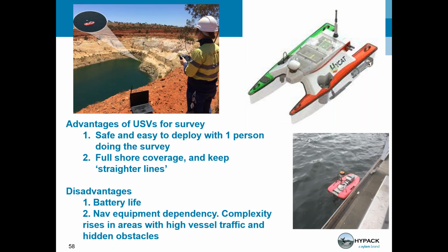Right, so for USVs, a lot of different USVs have been coming out in the market over the past few years, and they've been gaining a lot of traction and popularity among many survey communities. There are many advantages to USVs. One is that it's safe and easy to deploy with one person during the survey. And as said earlier, you can have full shore coverage because of the shallow draft. You can also keep very straight lines on your survey grid.